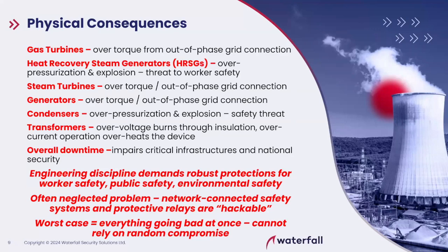So how do we use that in 62443? Well, we have to figure out the worst case consequences. And then we have to figure out, do we have electromechanical mitigations in place for these consequences? Because if we do, we can take them out of scope for the cyberspace. A common mistake that people make when they're assessing consequences in power plants is they fail to account for equipment damage.